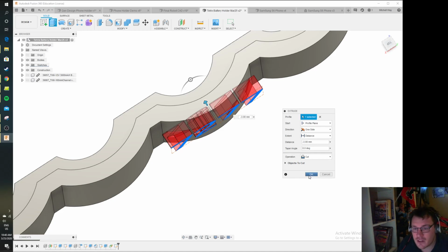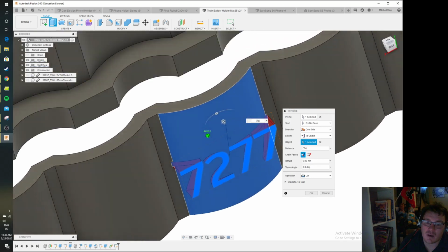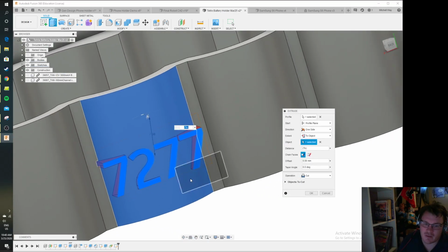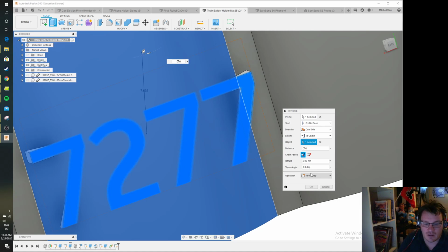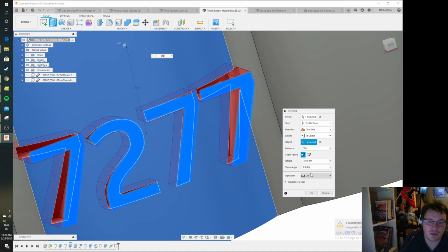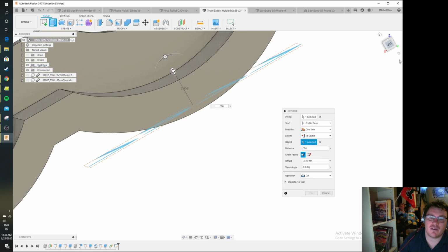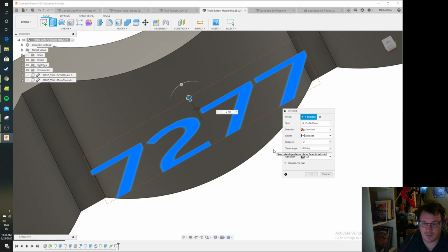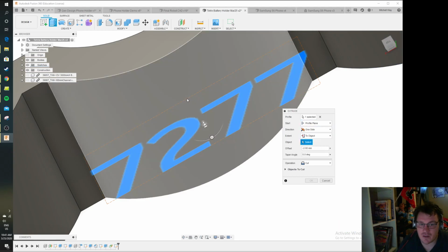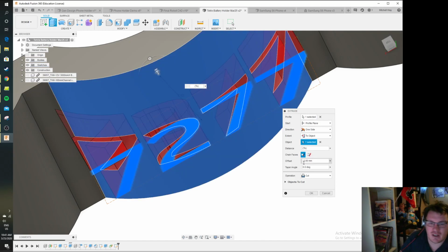Again, I apologize, guys. I thought I'd be able to get this cut all the way through. It might be because I've overlapped it slightly. Once I go to the object, I believe I can put an offset of 2 here. Oh, -2. There we go. I'm just going to check my overall spacing on this. Is that going to go all the way through there, which I don't really want? -2. Apologies, this is one I'm a little less practiced with. There we go. That's what we were looking for. So to object, -2 in this case.